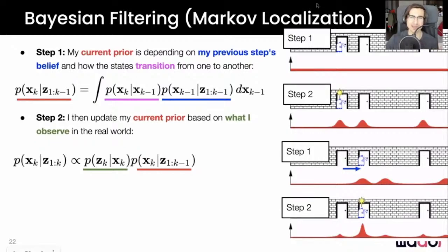since direct ego motion readings are typically noisy. And finally, in the second step of the second iteration, the robot finally observes another door and fuses this information with its current belief. This additional information helps us disambiguate the robot's pose, and it allows it to converge to a mostly unimodal distribution over its location. And note that this example is purely conceptual, since in practice, we usually cannot solve the integral from this formula in a closed form.